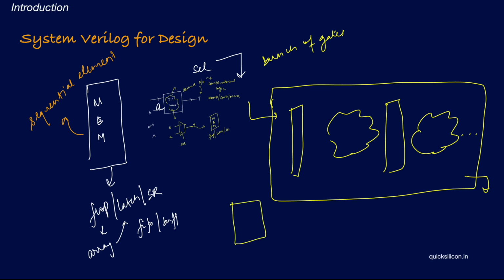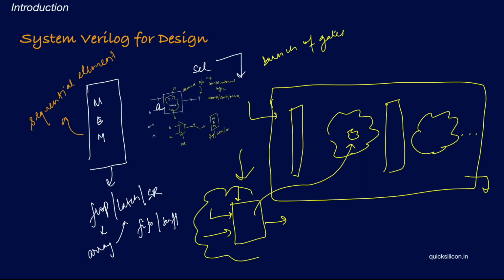not have any of the sequential elements playing a role because this particular mux would be part of this particular combinatorial logic sitting somewhere here inside, which is why it will just take certain inputs and then produce the output and be done with it. And you could have a single module which just does this. And the reason why you would have a module or a block for such a small design is to be able to use this particular block again and again instead of writing the logic whenever you need it. So that's why you would have this in a module.